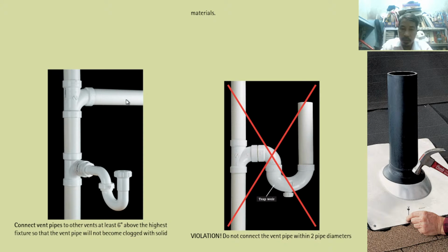being 6. So here, as you can see, this is about 1 foot or more than 1 foot, the distance from this point to this point, because you will still put in the fixture. The fixture will be placed right here like this, okay? And the maximum level would be about here. So this maximum level, flood rim level, up to that again is supposed to be 6 inches and more. Okay.